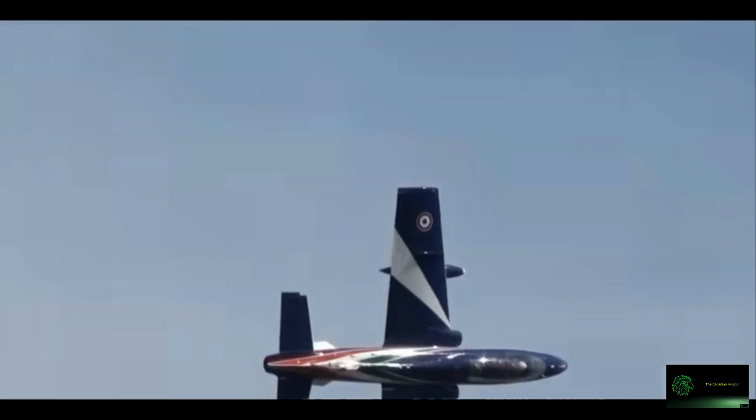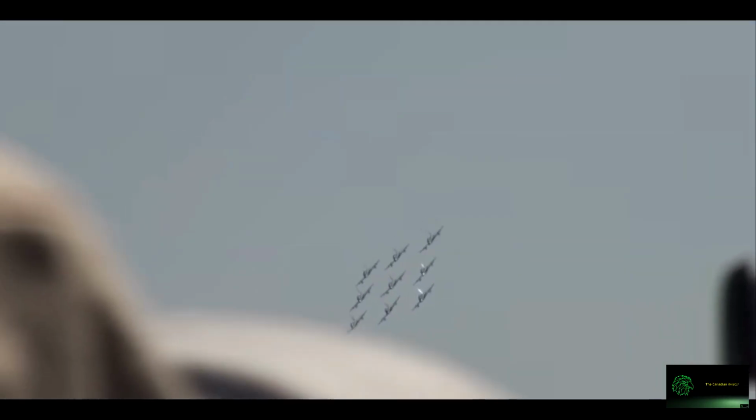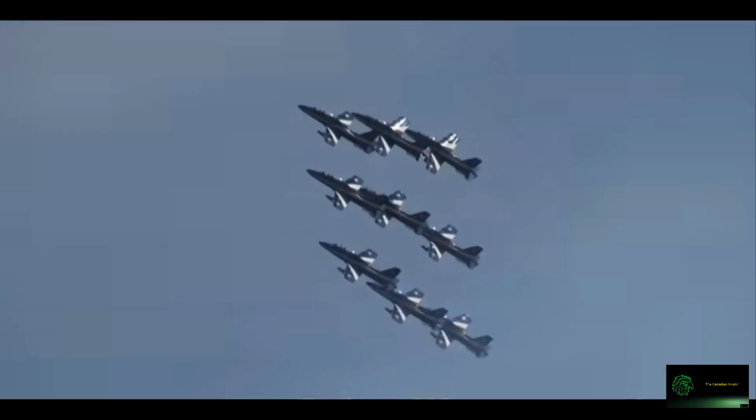VD is not shown on the airspeed indicator. Instead, the red line on the indicator represents VNE, which is set below VD to ensure structural protection in normal operations.